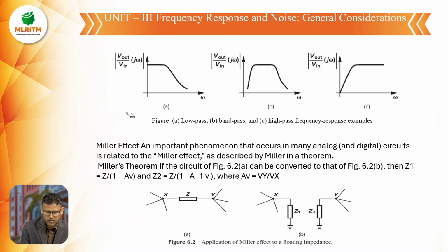First, low frequency, which is nothing but the low pass filter frequency response. The low pass filter response is high at the zero position, and as the radial frequency increases, you can observe the voltage gain on the y-axis is constant up to a point, after which it slowly falls. This indicates the relationship between frequency and voltage gain.